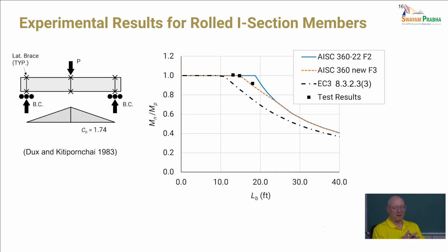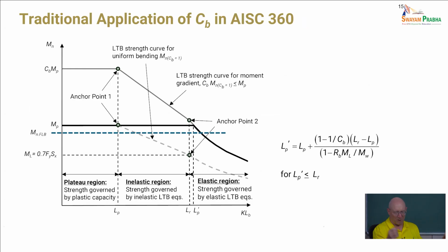If you had a case with reverse curvature bending, what I see from FEA is that, yeah, it's really getting suspect. So we're suggesting that we should put a cap there on the way that we use section F2 to not allow this very simplistic scaling. It works well up to a point there, but I think once we're getting to higher slenderness values, it doesn't work so well.